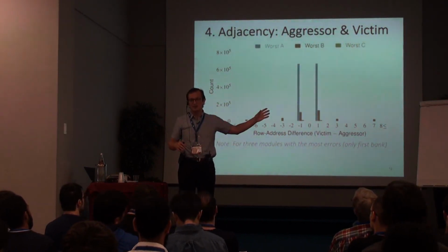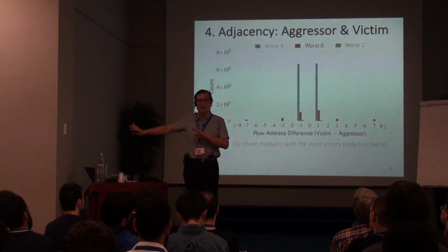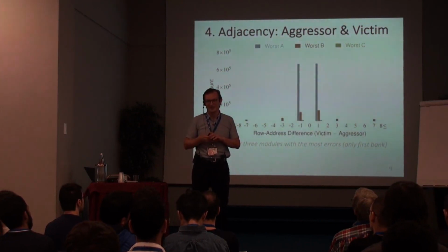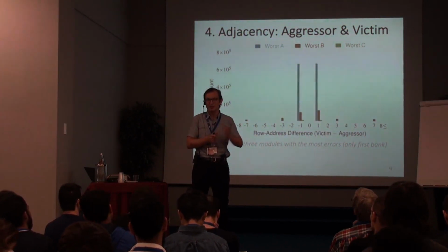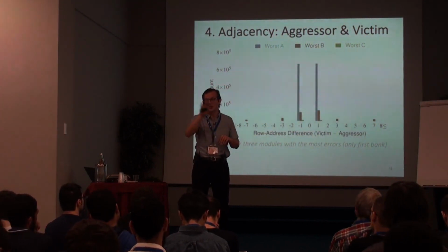Even if the controller sits outside, Rowhammer can be solved with existing controllers, existing systems, without changing DRAM at all, if you have an intelligent controller, basically. But I think there are trade-offs between having the controller in the DRAM, or in the logic layer underneath the DRAM, or on the processor chip. But this is going to be a hot research area going forward.